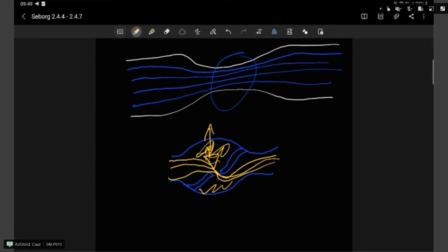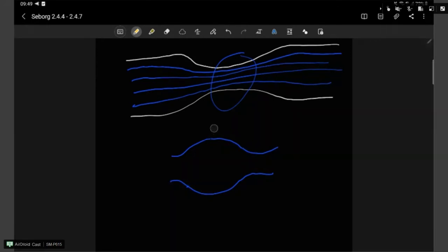So you can't really assume it as something that would be valid for assuming the Bernoulli equation. In the event of a gate valve, let's say a gate valve that is fully open, you have this entire surface or volume that is open to that, and your streamlines develop more properly. So that can be assumed as, let's say, an orifice. So some form of a restriction, but one that doesn't hamper the streamline formation.